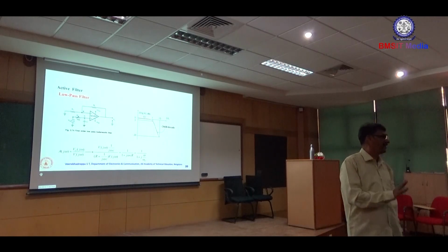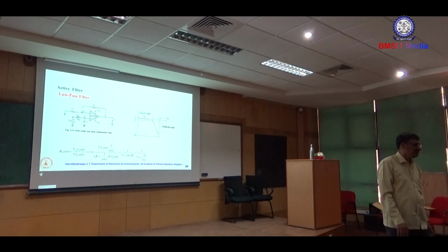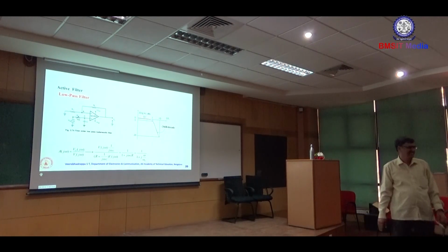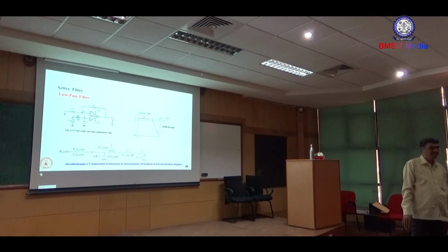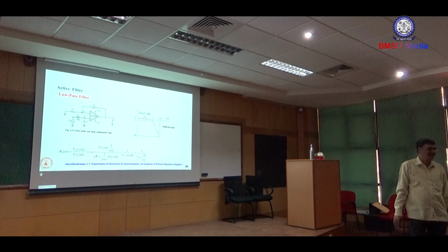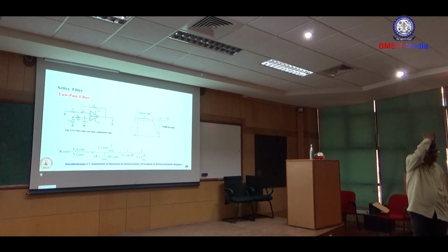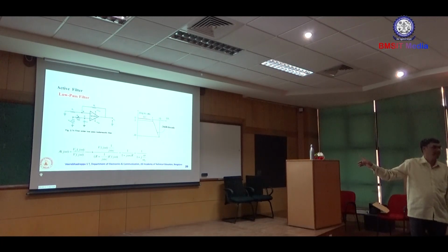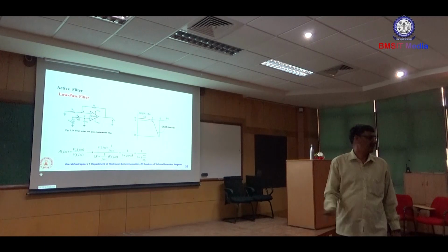Why do you have to choose half power only? Next question: why do you choose only 3 dB? You have networks in your subject? You study maximum power transfer? Yes, sir. What is that condition? Input resistance equal to load resistance. If the input is not equal to the output, what happens? What is the effect? The power gain is reduced. What is its implication? This implies that at 3 dB, there is impedance matching between the input and the output, the source and the input stage. Because of that reason, we always use the 3 dB bandwidth cutoff frequencies.